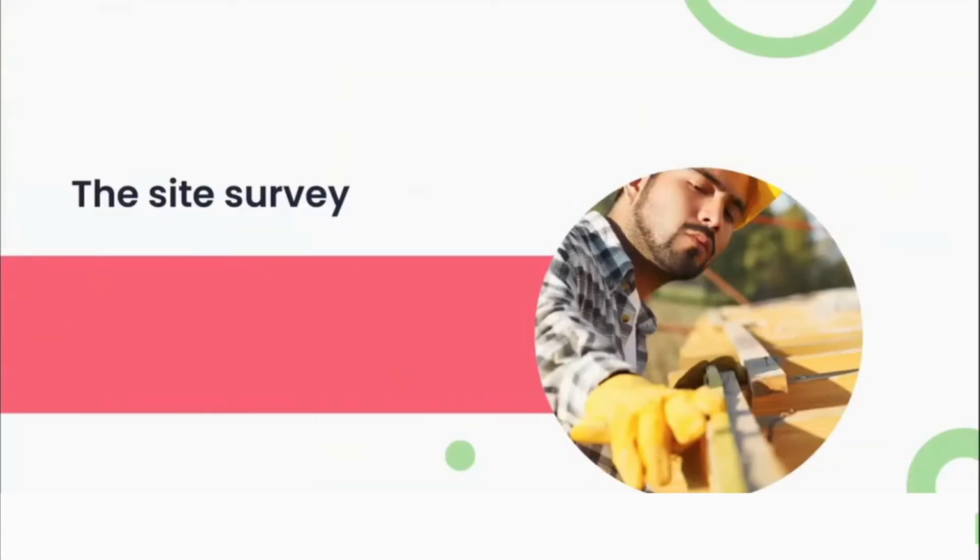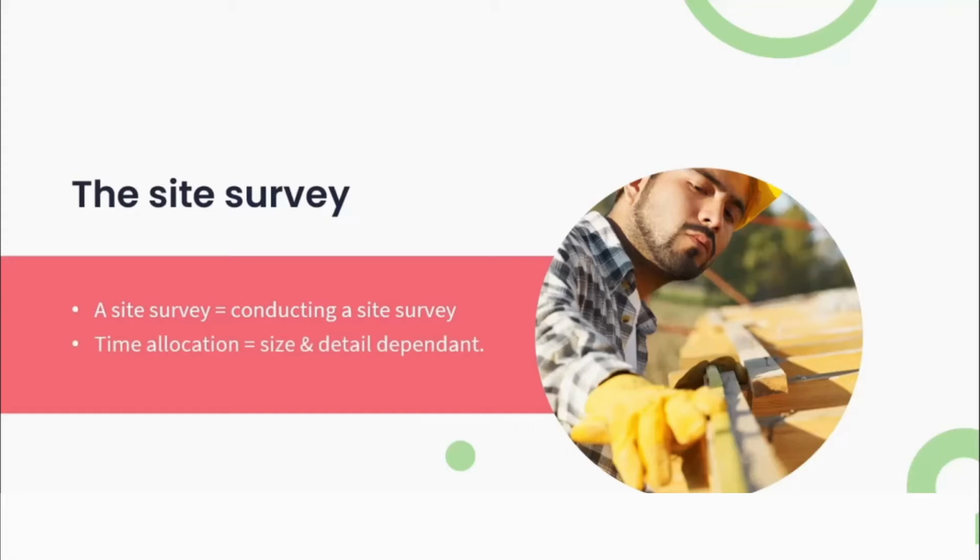In the design and architecture industry, a site survey would typically be referred to as conducting the site survey or conducting your survey. A site survey can take from anywhere between 30 minutes right up to an entire day. The amount of time spent on your survey would be entirely dependent on the size and the amount of detail that is required on that project or site. Remember, you need to document as much information as you possibly can relating to that project. You want to include everything from the ceiling, wall heights, right up to plug locations and furniture placement, and maybe even plumbing and pipe work.